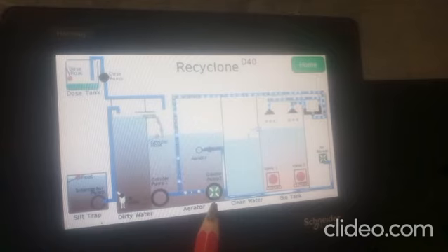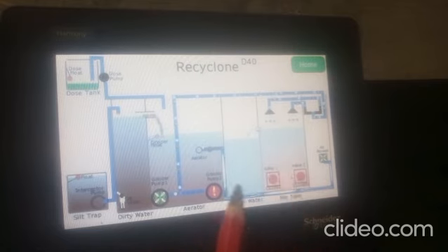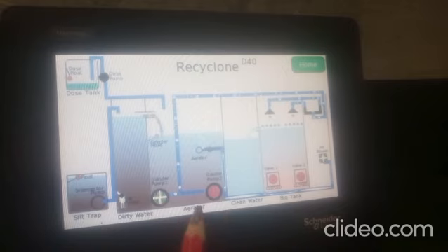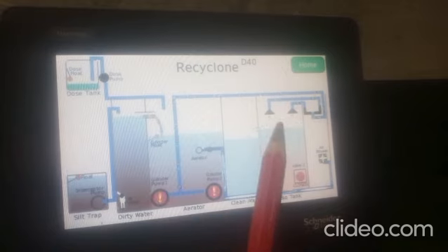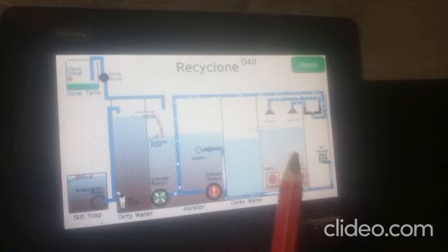In the event of a trip, the other pump automatically kicks in, and this animation shows this connects up to these sprayers up here filling the biotank. If both are tripped, the sprayer animation will also cease and both of these alarms will be indicated. We have our clean water tank, which is being filled from the biotank only when the sprayers are active.